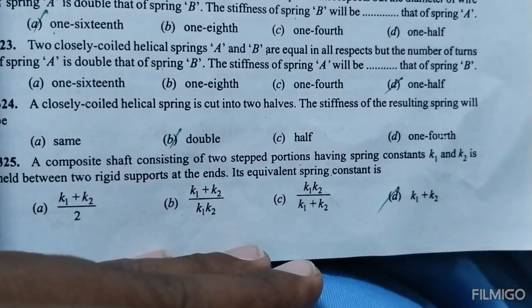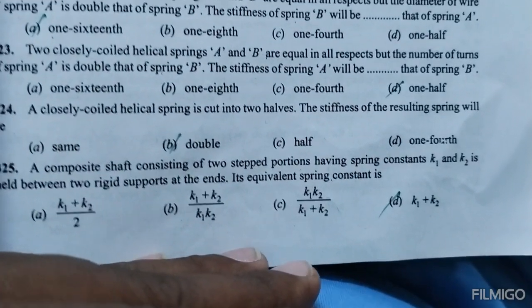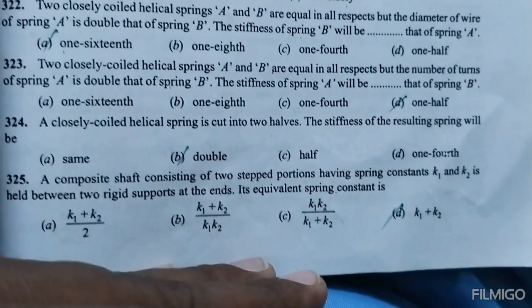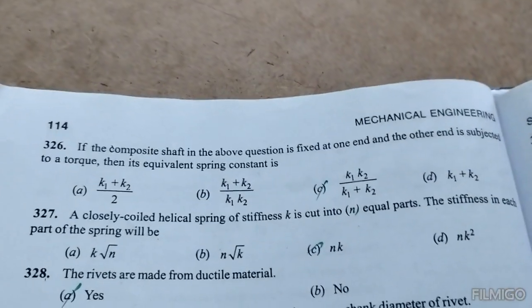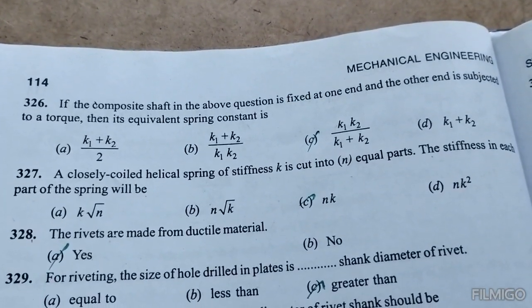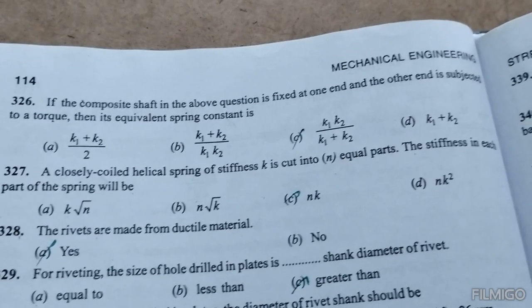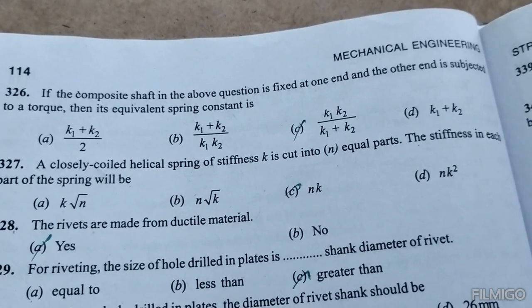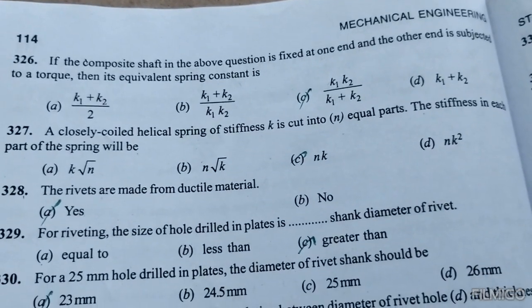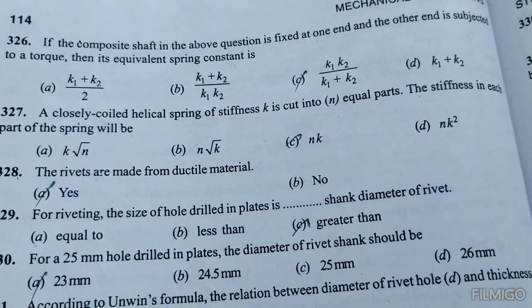A composite shaft consisting of two step portions having spring constants K1 and K2, held between two rigid supports at the ends. Its equivalent spring constant is K1 plus K2. If the composite shaft in the above question is fixed at one end and the other end is subjected to torque, then its equivalent spring constant is K1 K2 by K1 plus K2. A closely coiled helical spring of stiffness K cut into N equal parts,